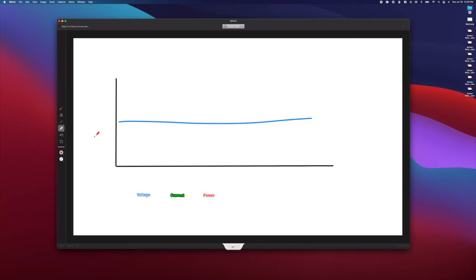Okay, let's talk about constant current, which will be very easy to understand now that we've gotten through the mess of the first one. So we have constant current. We are going to measure the current in the system and adjust the voltage as necessary. And because the relationship of volts and amps has not changed since we drew our last graph, when you have the same amount of amps and less volts versus the same amount of amps and more volts, the power graph is going to follow that as well. So one remains the same, two change, they are all in proportion to one another.